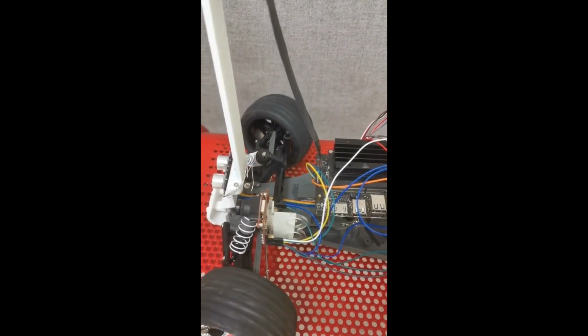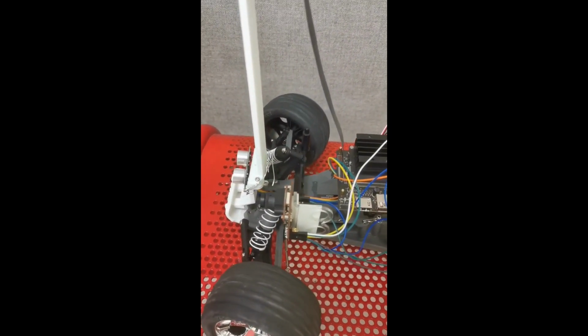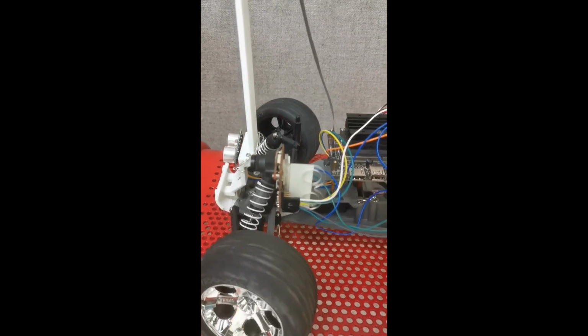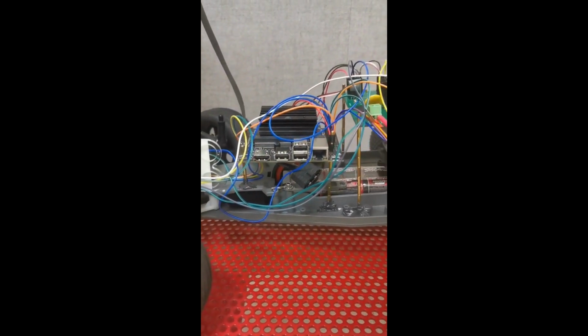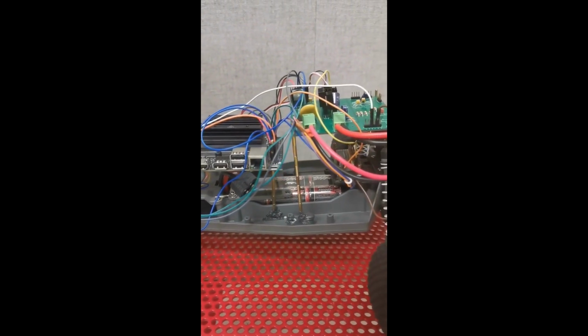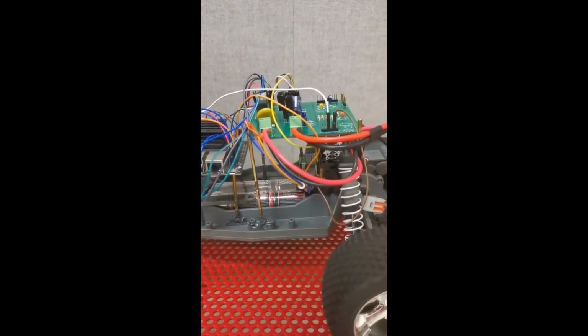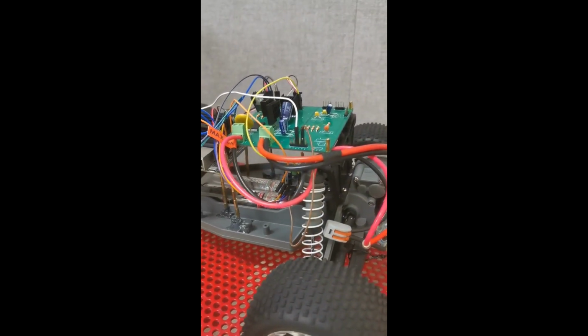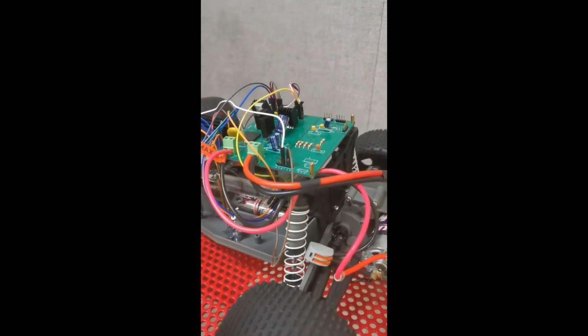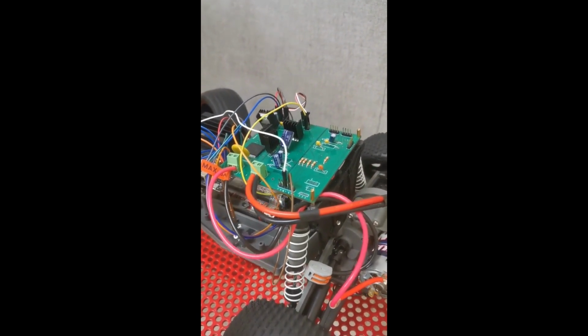Since the motor needs to be run at 1K to 2K Hz and the servo at 50 to 100 Hz, while the PCA could only have one frequency value, we had to use the OpenMV too. We set the frequency of the PCA to 100 Hz for the PWM signal of the servo, and the OpenMV to 1.5K Hz for the PWM signal of the motor.